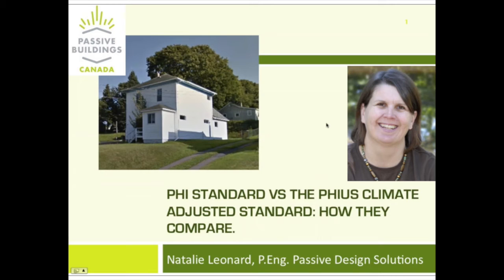I think the final air tightness was like 0.43 on that project, so that helps quite a bit. Second, it's quite high density, so it's 4 occupants in a relatively small building. So our energy budget was quite good. We just had electric heat and a hot water heat pump, Energy Star appliances, nothing really special on the appliances, and we reached the PE.